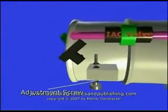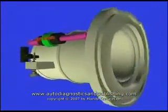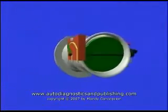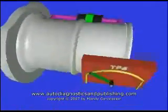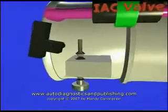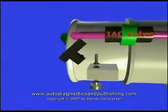A minimum air rate adjustment should be performed any time the vehicle is stalling during a loaded idle condition, such as when the vehicle is idling in drive with the air conditioning on. The minimum air rate adjustment simply entails synchronizing the throttle plate screw, idle air control valve or IAC, and TPS to achieve the desired idle condition.